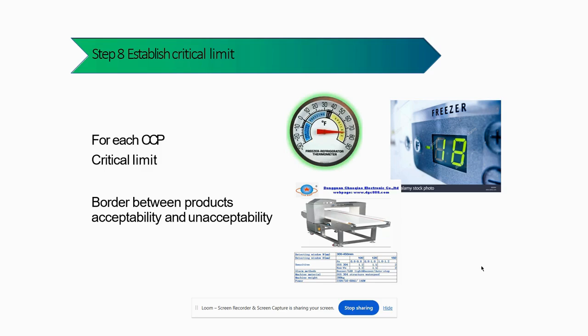This magnetic separator, we can fix at different locations in the process flow of the material. We can periodically take out the magnetic separator and collect how much iron and iron particles are collected in the periodic time interval. So that could be considered as one of the critical limits. If it is more than a certain level, we can ensure that it is beyond the critical limit, and we have to take appropriate action. Let us discuss that in detail.